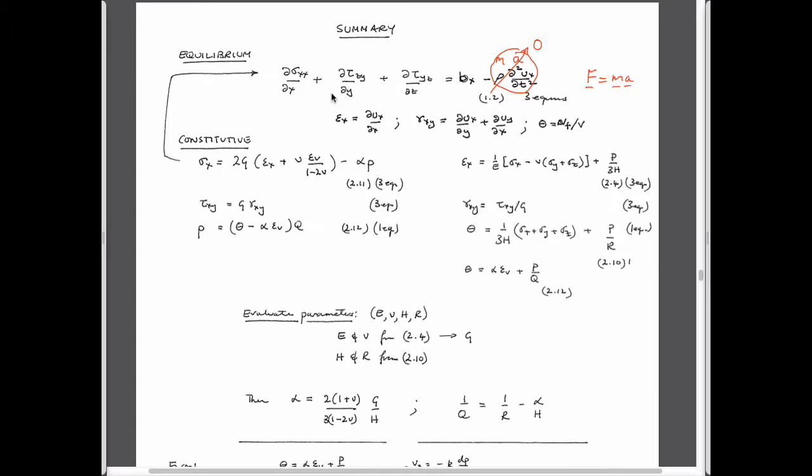They have a continuity relationship. Continuity says that as you go through the system from one point to another, all the dependent variables are continuous. Displacements are continuous. They don't have jumps in them. Fluid pressures are continuous. Concentrations are continuous, or temperatures are continuous for the four classes of problems.